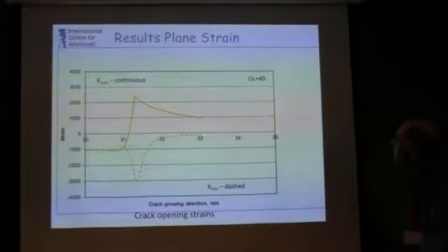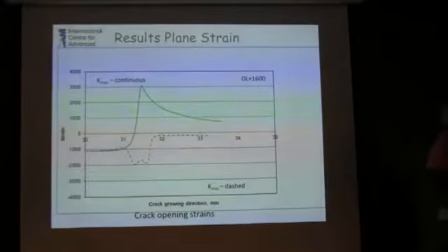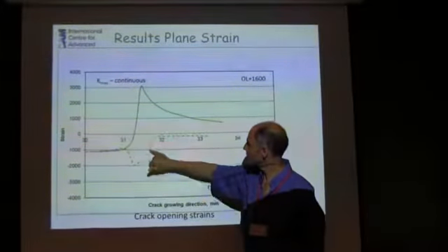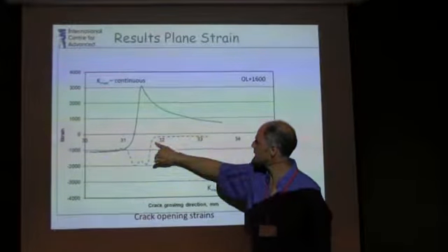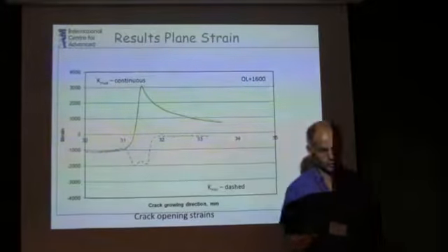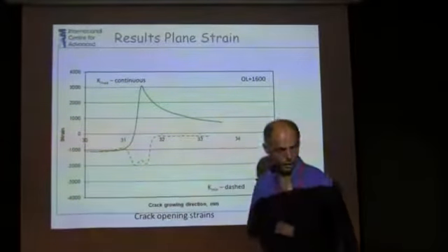And then as you grow the crack out, you can see as the crack grows further. Now, this is interesting. At this point, you've grown the crack a little distance, and you can see the compressive plastic zone that you'd expect, but you can also see another one. There's definitely a double kink there. So this is the original location of the overload, and this is just after overload.